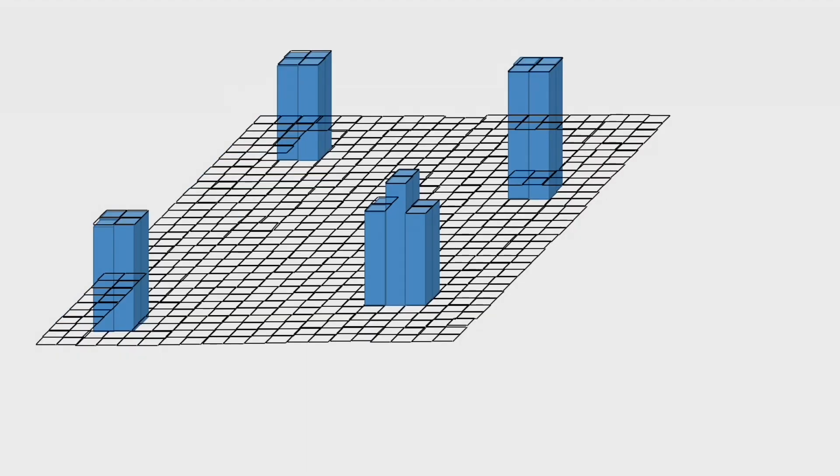So let us say these are the grids we have generated, and now if I remove these buildings, this is the DEM. Each and every grid is telling some height information as well as the XY information where it is situated, so the planimetric location XY and the Z information. If I use DGPS, these heights are indicating ellipsoidal height. But if I use the orthometric height in my GCPs, then these heights are indicating the orthometric height of the building. This is the footprint of the building here.